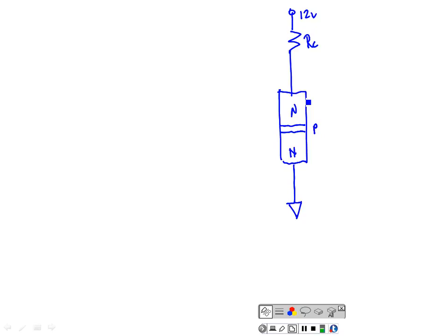They're living by the grace of God. So what you're supposed to do is hook up your red lead first and then hook up your black lead somewhere away from the battery, like on your bumper or on a big metal chunk of your engine. But, don't do that.